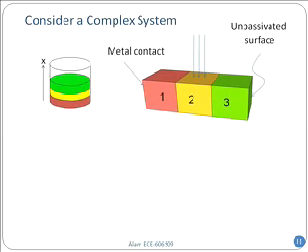So consider that I have a crystal, and this is blue, and as the crystal is growing, I'm incorporating a different amount of dopants maybe, or the temperature of the crystal is changing as I'm growing it. So the bottom line is that because of the growth process, these regions have different properties. The red region is terminated by the metal contact, and similarly the green region on the right, the third region, is also terminated by a metal contact. You must have 2 contacts so that the currents can flow.